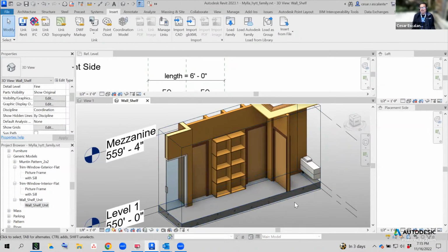Yeah, so this is just a small sample of what it is to build a fully parametric family. The same logic or similar logic would apply for wall cabinets in the kitchen. If we're talking about a wall cabinet, then we would add the door as a nested component, and then lock the width and height of the door to the parent parameters. The handle is another nested component. The glazing could be another component with a different material. And then you can build an entire library of components just by being smart about how to assemble and nest one component inside another.